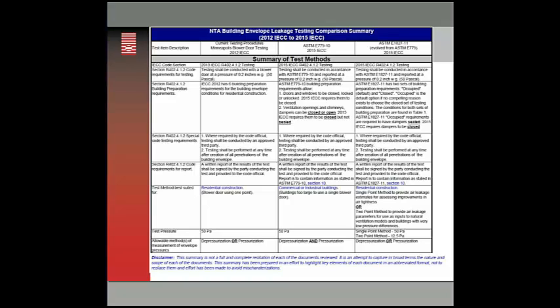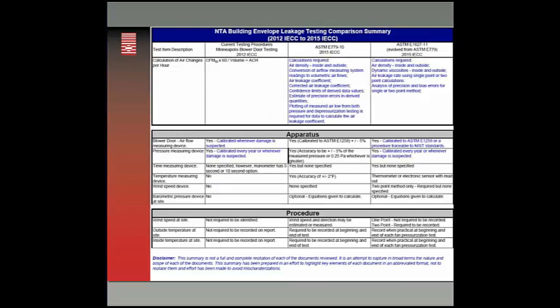779 as a one-point test that you can do. On 1827, you can do a single point or a two-point method. Some of the other requirements, really, for the codes right now, all the codes are requiring is that you calculate air changes per hour 50, ACH 50, CFM 50 times 60 divided by building volume for ACH 50.